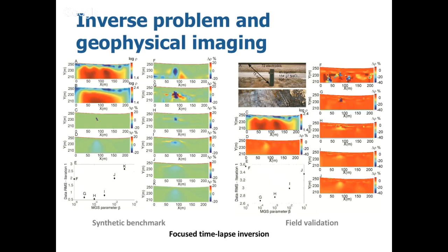We finished in 2012. If you do a smooth inversion and then a difference inversion, you will find this. This is the background. You see the limestone with high resistivity and the top layer of unconsolidated sediments with lower resistivity values. And you see a faint image here, which is the signature of the salt tracer, with percentage changes of about minus 15%. This is what you would get equivalently in numerical modeling. Because we use a smoothness constraint approach, you get the smoothest blob.